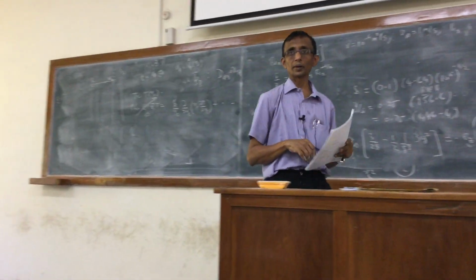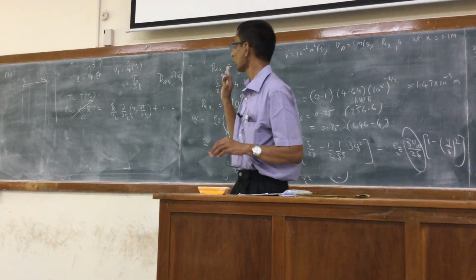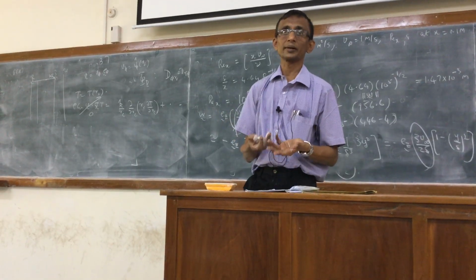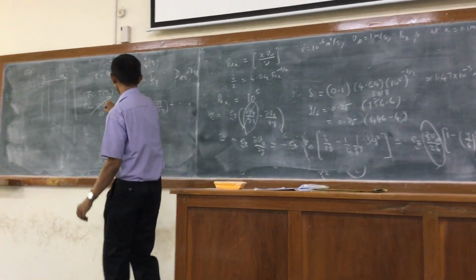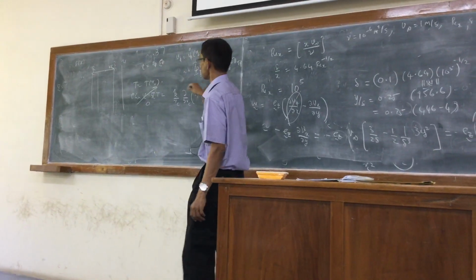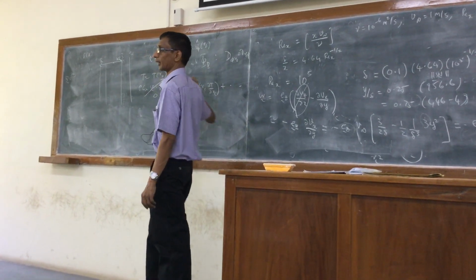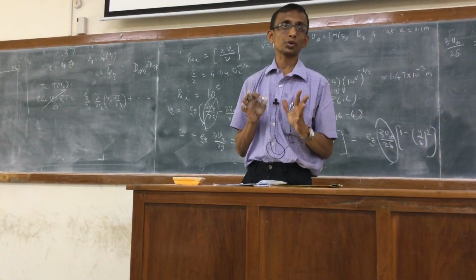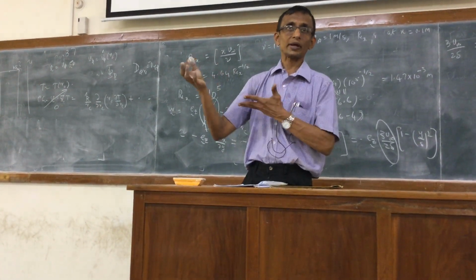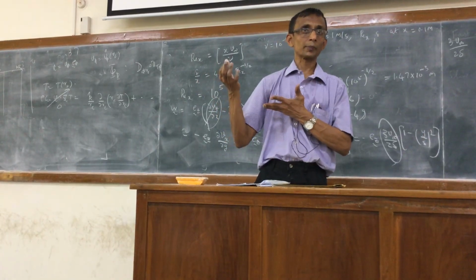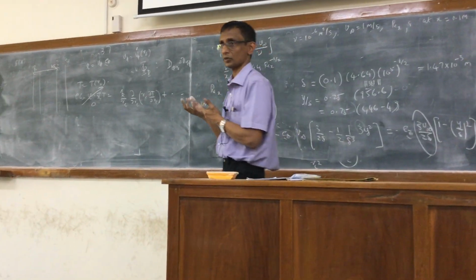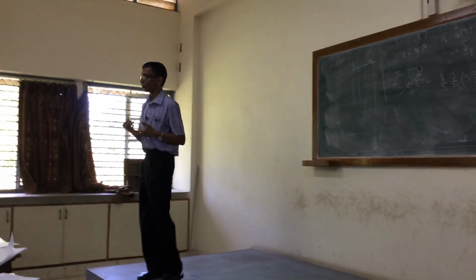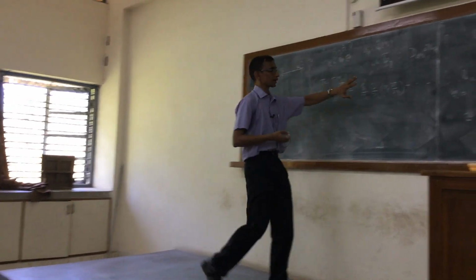You will find because the V is only the phi component present, the temperature doesn't have any variation in the phi, you are assuming it, right? So you will find that this term would be 0. So you get an ordinary differential equation in T in terms of r. And of course, if you neglect the viscous dissipation term, we get pure conduction without any motion of the fluid. That is very standard in heat conduction problems you would have done. Solid heat conduction normally, right? Where only conduction is there. Here, because the fluid is stationary and not moving, that is what you would get.